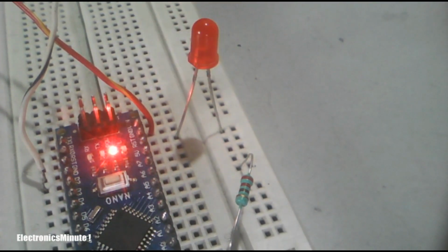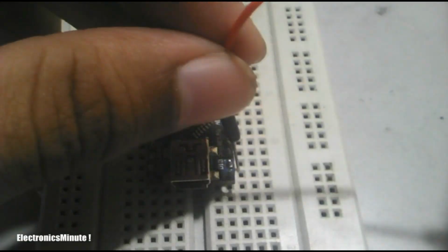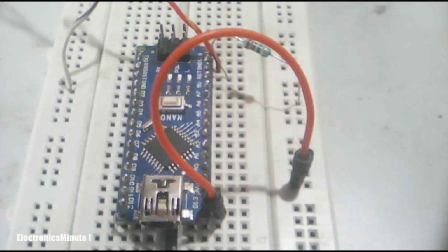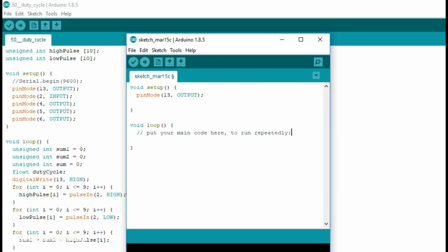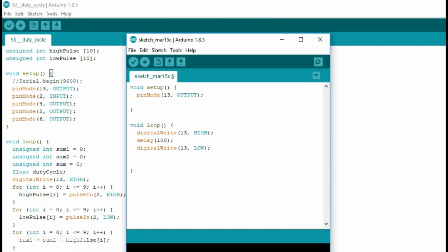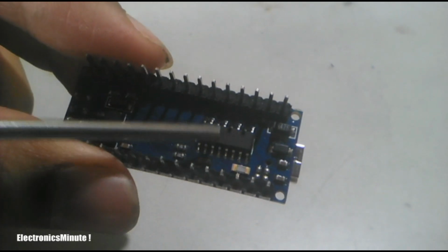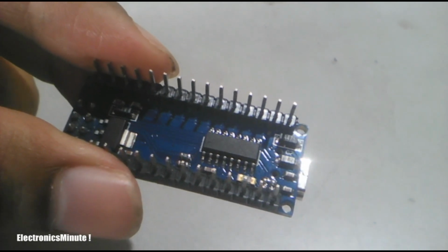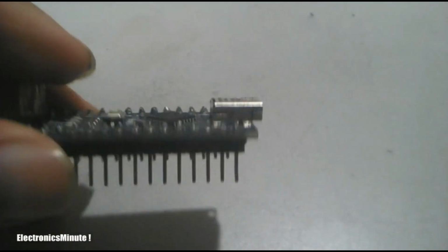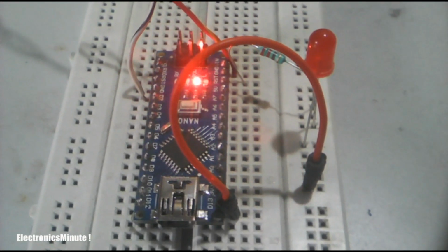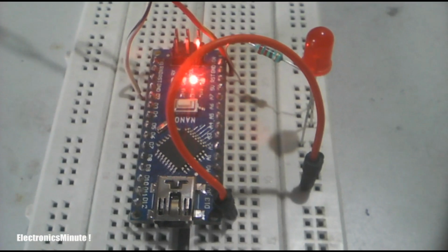Then my curiosity increased: would the Arduino Nano be useful for any electronic project? So I continued by creating and uploading a new code in the usual way. Then I got this. After trying a few more times, I realized that the USB to serial converter of the Arduino Nano may not be working, or maybe it has a different converter such as a Chinese one, so that the Arduino IDE does not communicate with it properly.